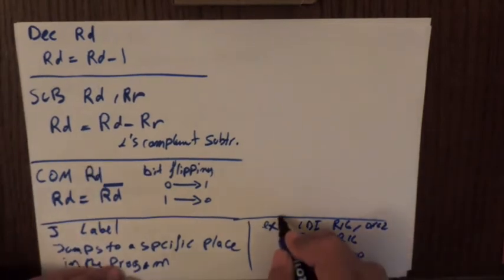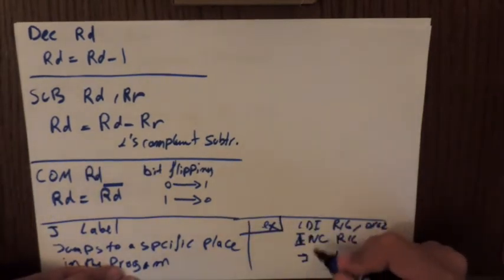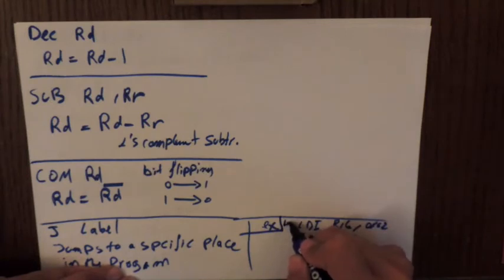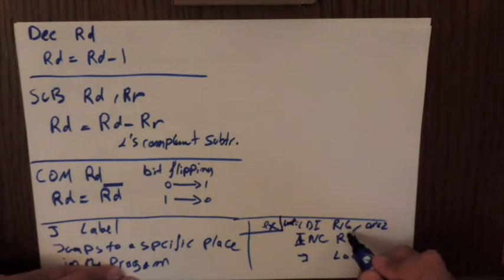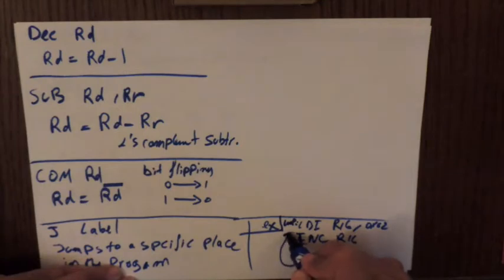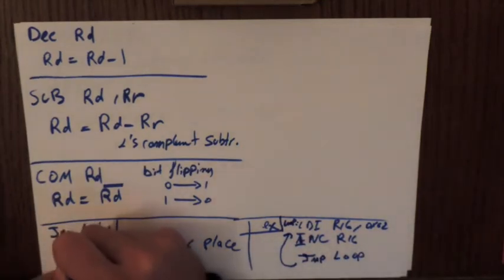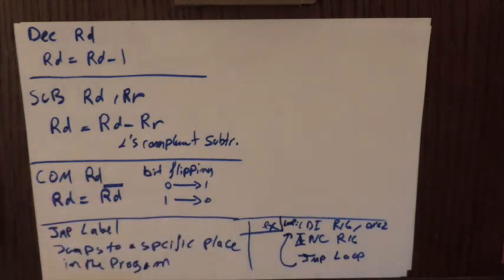So where is loop? I need to place it somewhere where it jumps, so I put loop here. So what happens is I will read into R16 0x02, increment it by 1, and then jump again like this. So it's actually JMP, not J, JMP. So jump label. So I will do this over and over again until infinity. So this is an unconditional jump. It goes and repeats this program over and over again.